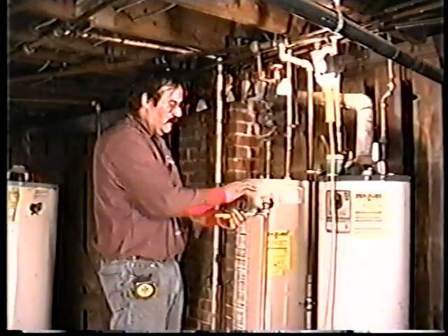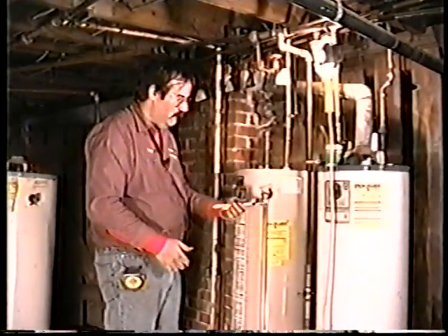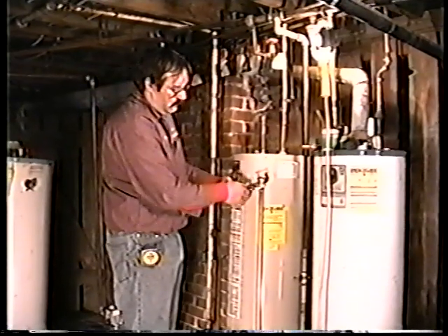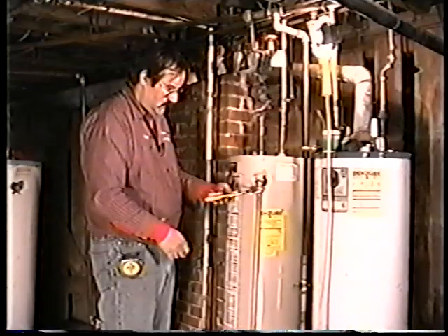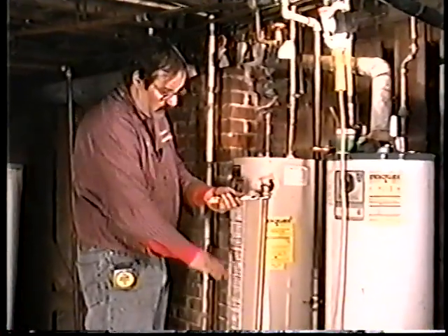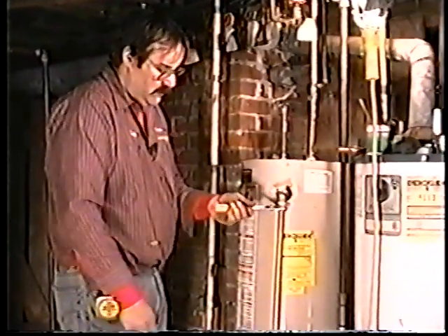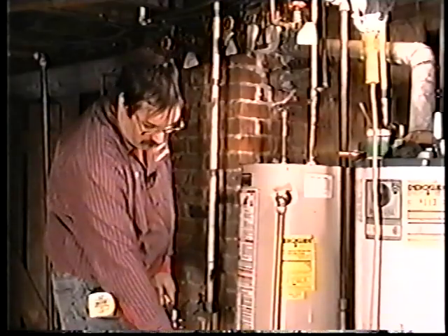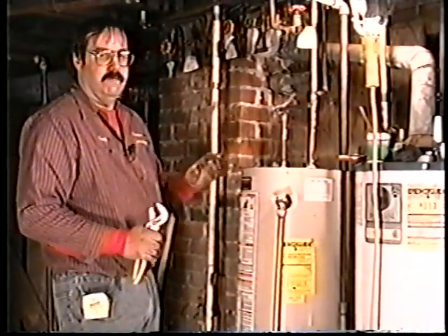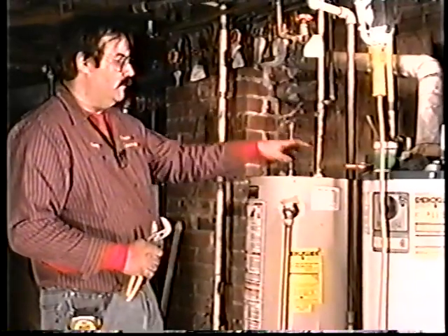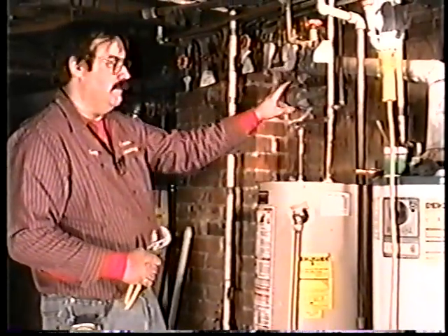The line from the relief valve is threaded into the outlet side of it. Okay, have some pipe compound on there to make the joint secure. And that has to, like I said, go down towards the ground. Certain codes have certain restrictions on that distance from the ground to the bottom of the relief valve outlet. Final step is going to be to attach the flue piping from the water heater to the chimney.